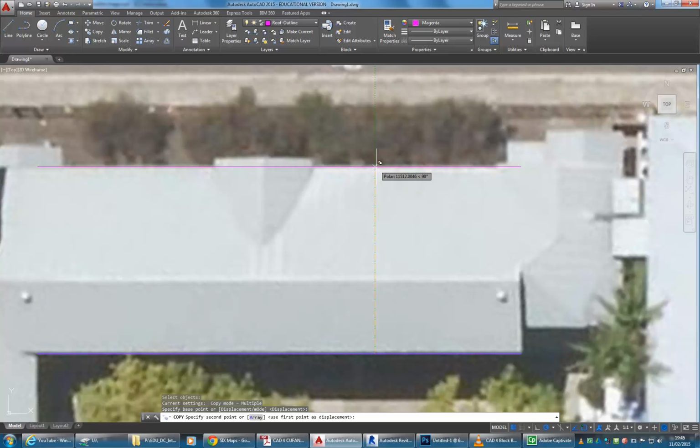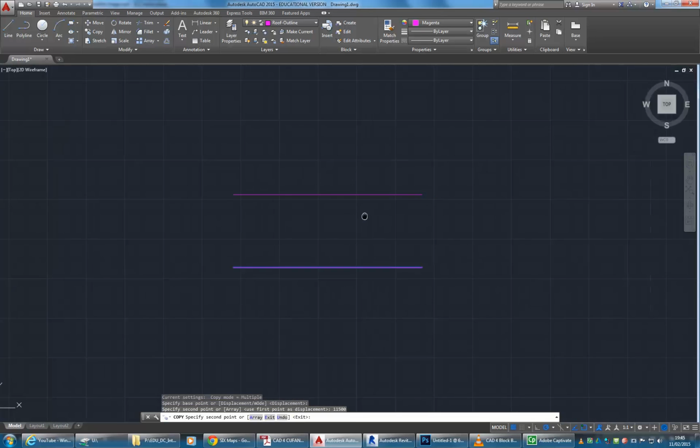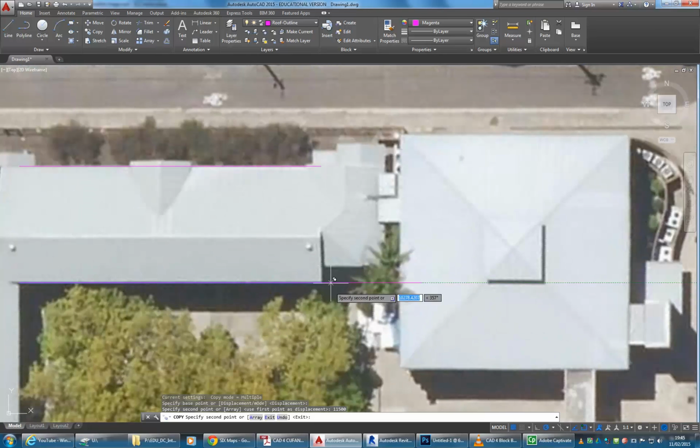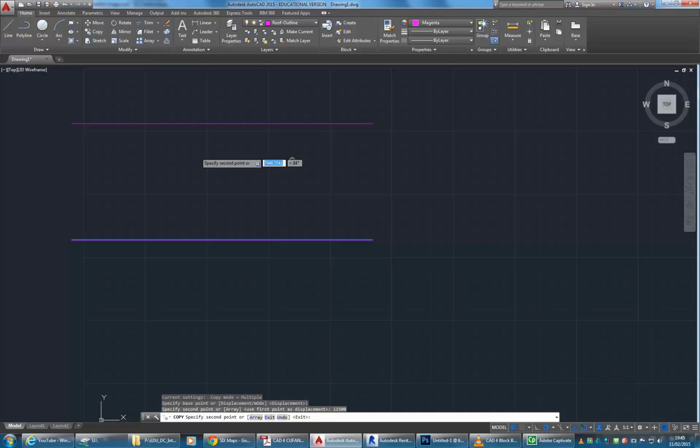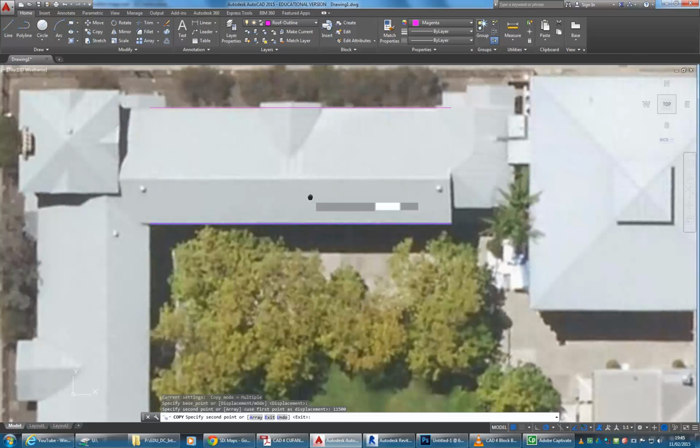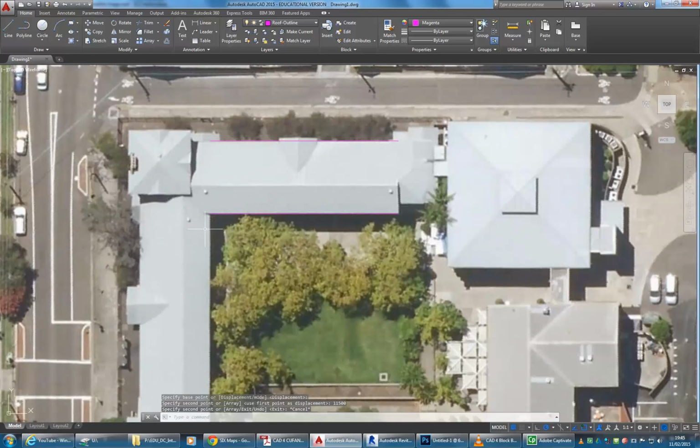512.0046. And when we're working in Revit and we turn all of these things into walls, we want things that are again using more logical or rational measurements. It would have all been built using imperial measurements anyway, so you're going to have some funny numbers when you go and measure the bricks, but again you can always round that off as well. So here I'm going to type 11,500, enter. I've got a copy of the line, and I can use a similar approach for a lot of these others. It doesn't always need to be like that, but the more you do this, the more rational you make the measurements, especially for the parts you're going to work with. So I'll press escape now.